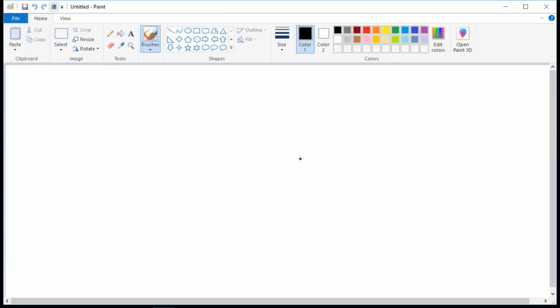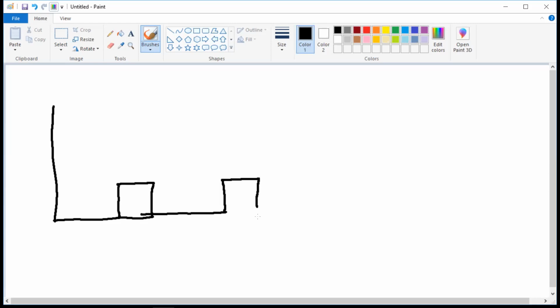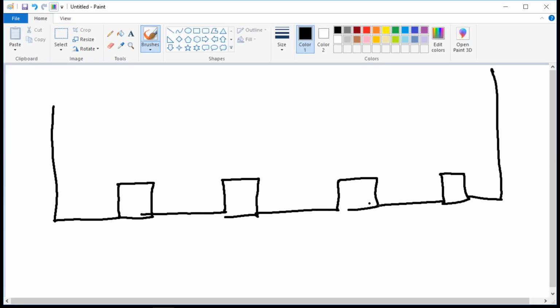All right, little quiz here, stand by. Not graded. That designates normal open point. Transformer 1, 2, 3, 4. Fuse. Blown. Red. Red. White. Where's the bad span? Between 2 and 3. Okay.